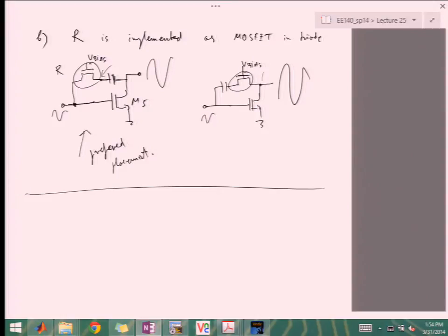And you'll see in your lab 3 designs when you start playing with Miller compensation, if that's what you choose to do. And you will likely be forced to simply because of the kind of bandwidth requirements and the settling time that you'll have on the closed loop design. Then you'll have to toy around with these kinds of arrangements and make sure that you pick the right values for the R in order to turn the 0 into what you need it to be, right?